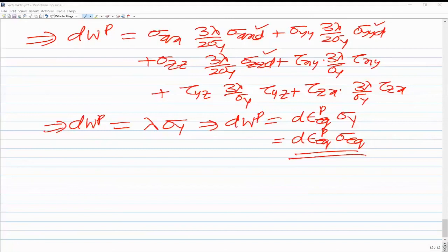The shear deformable plate using FEM, twisting? Yes, at edges we have it separately. In the boundary conditions and the internal load vector, we have twisting moment Mxy, or Mns. But not in classical. In classical, Mns is clubbed with Q and denoted as V. If you remember, I would have denoted it as V. Okay, so the twisting moment gets carried on to the normal moment and the shear moments.